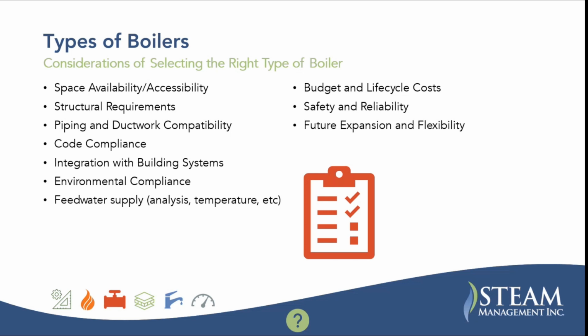Other considerations, space availability, accessibility. I mentioned the cast iron boilers. That's a big thing. If you have a cast iron boiler, a lot of times those boiler rooms just have a stairway or something to access the room. And when you go look at a completely assembled package boiler, which most of the condensing boilers are going to be, you may have trouble getting that into the space.